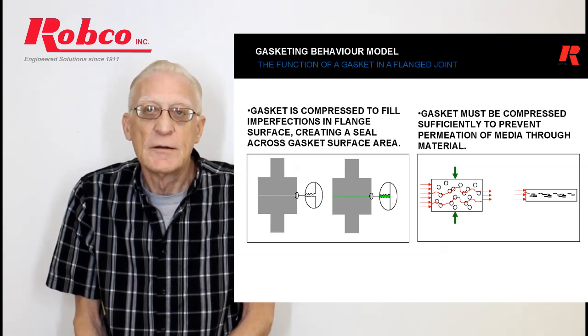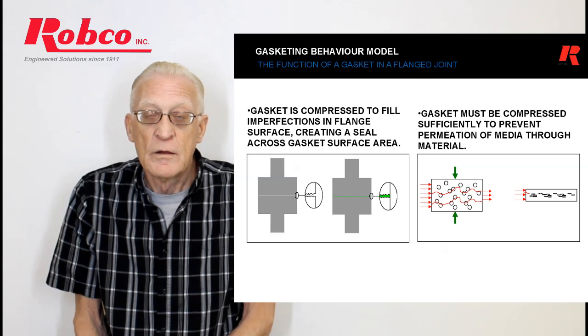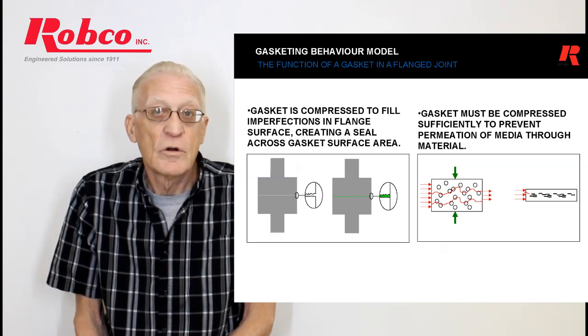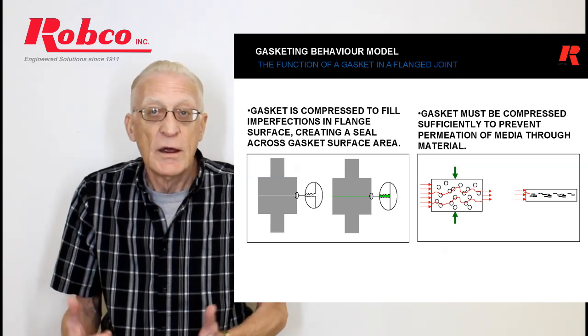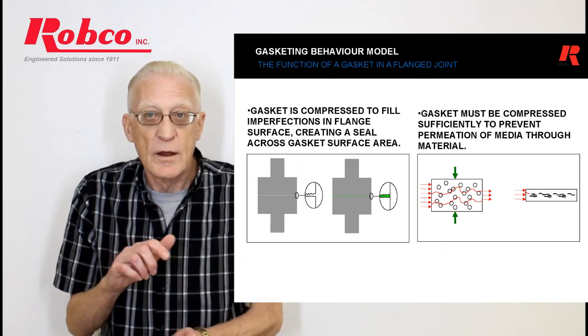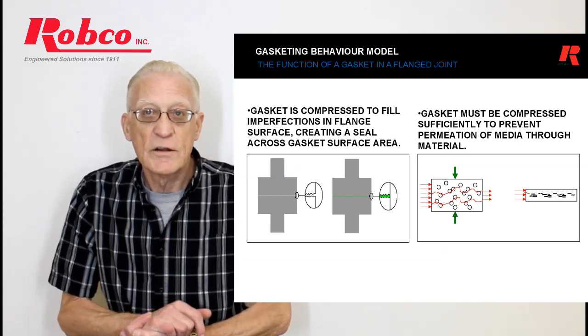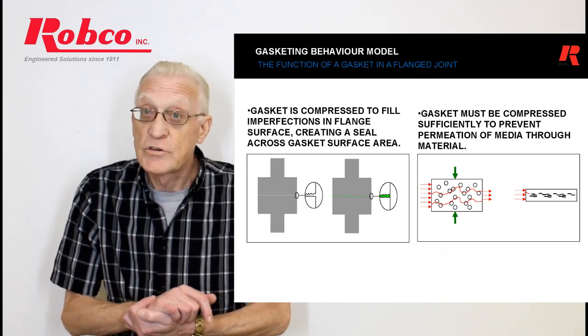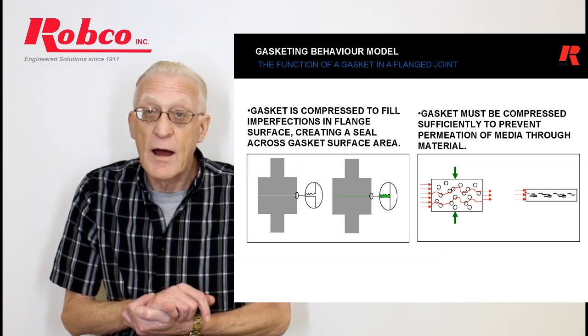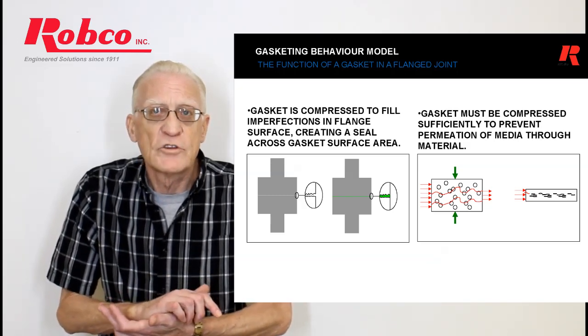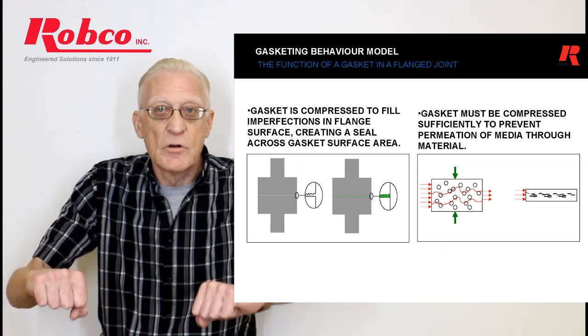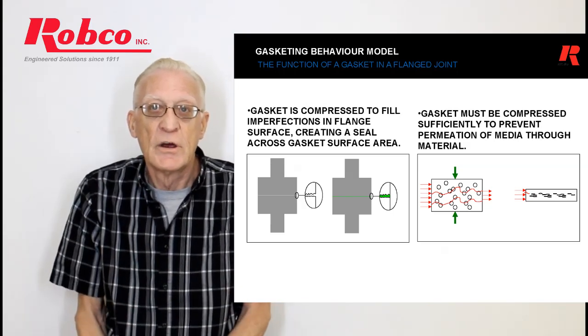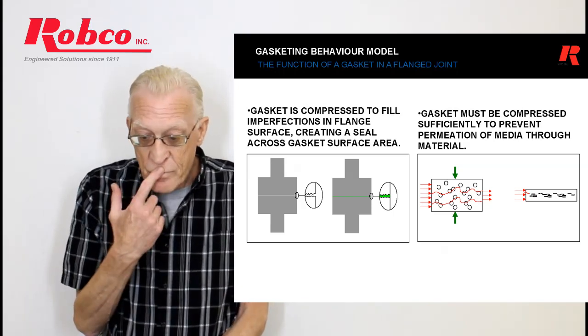How deep is it in microinches? So a standard gasket will be 250 RMS flange. It has enough depth and enough material to grab onto that so that the internal pressure I was talking about before doesn't blow out the gasket. The gasket's actually grabbing onto the surface of the flange, and that's how it's designed.